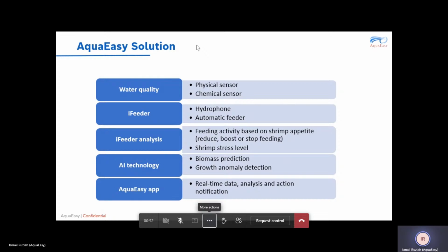And the last thing is the power failure check. Basically, we will trip the panel and see if the panel can restart on its own, and every program is running back automatically. And also the UPS function. We have a UPS for the panels. So when we trip the panel, the UPS should turn on and continue the panel functions until it dies out. Normally a UPS, I think at most it can run 30 minutes. That's the most.